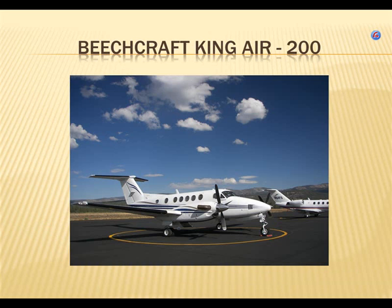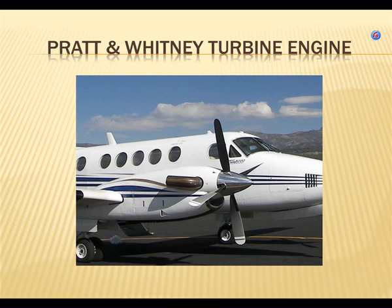Okay, turbine engine. There's one on the Beechcraft King Air. There's an up-close look at it. So a turbine engine is a jet engine with a propeller, right? Now, that might be carrying it a little too far. It is a jet, and does have a propeller on it, but it's not quite the same as the jet engines of today. In a jet engine, the air goes in one end and it blasts out the other. Well, here the air comes in, goes all the way through, and comes back and is exhausted out here.